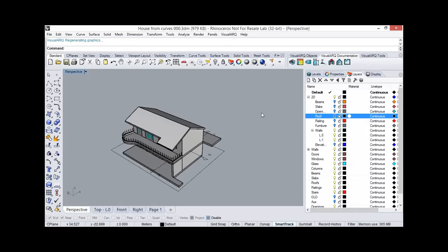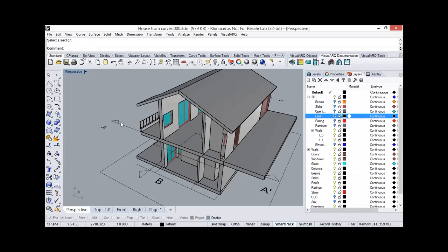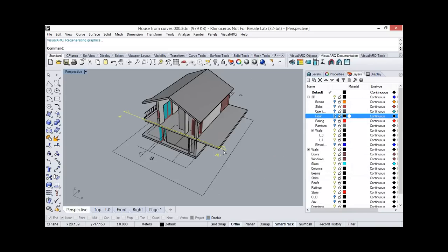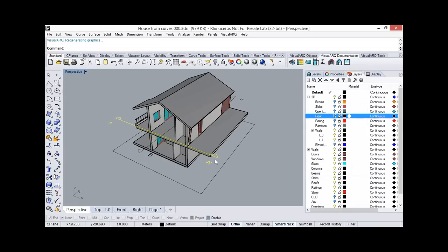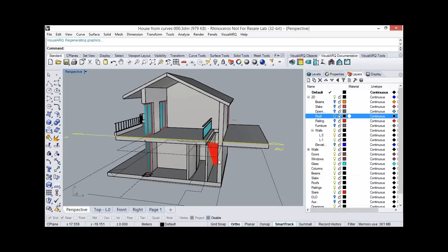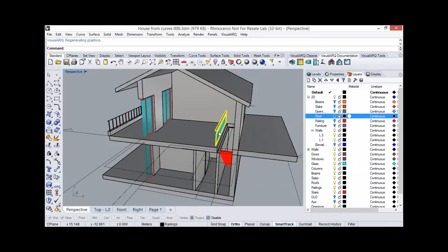Once I have the section lines created, before creating the 2D section view, I will show you the dynamic section command, which shows me the model section in real time, according to the position of this section line. Okay. Wherever I move this section line, the project updates. Also, this makes it easy to get very interesting views from the project I'm working on. Also, to work from the inside of this project.